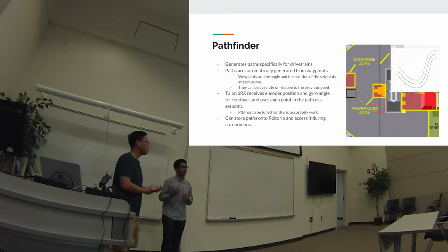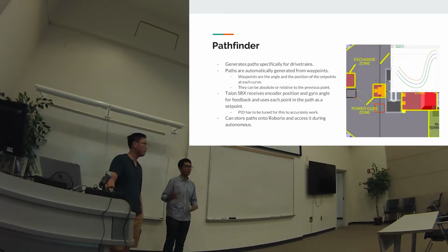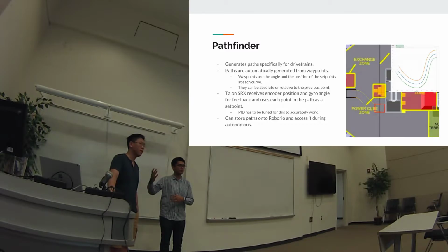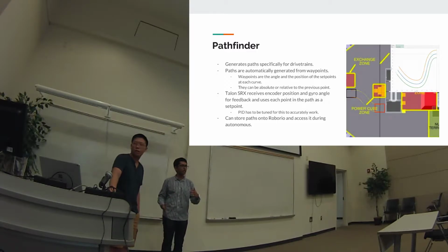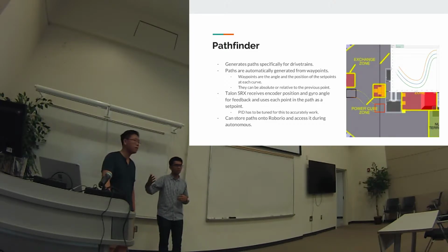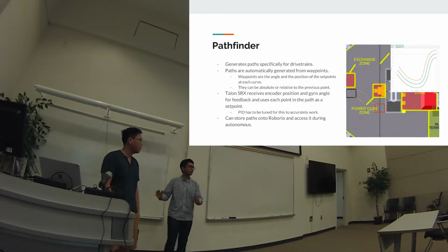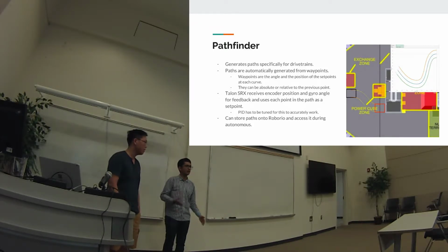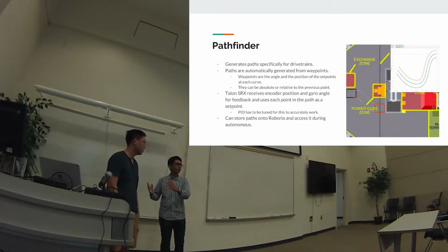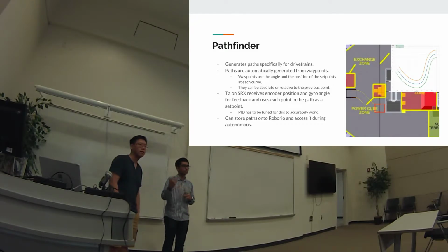Because of that, when you're using Pathfinder, you'll realize that one big limitation is, like we said, open loop isn't very repeatable. Pathfinder has a similar situation in the opposite scenario, where it's not repeatable because you have to tune it so accurately. For example, when we were running around the switch to go to the other side of the scale Pathfinder path on our robot, when we did it on a practice robot, which is just a drivetrain, it would go there perfectly, but on the actual robot, once the elevator starts moving up, it would go offset, and sometimes it would hit the wall, sometimes it would go around, and we had to tune it over time. So tuning Pathfinder, the cruise velocity and acceleration with your elevator, is also as important as tuning the PIDs.